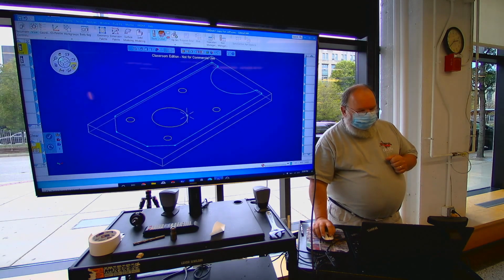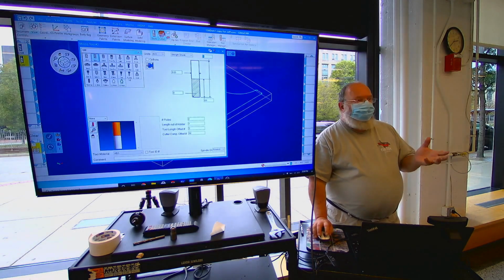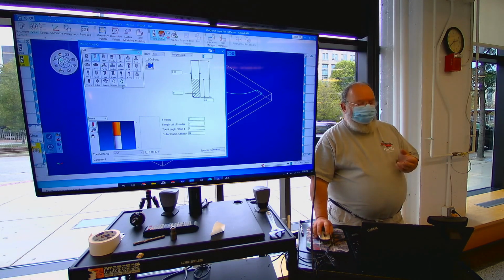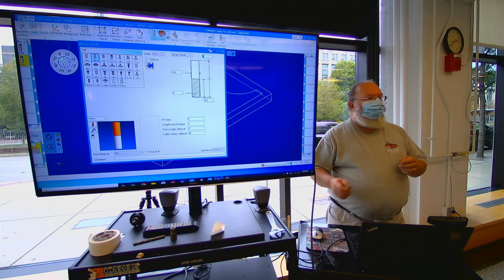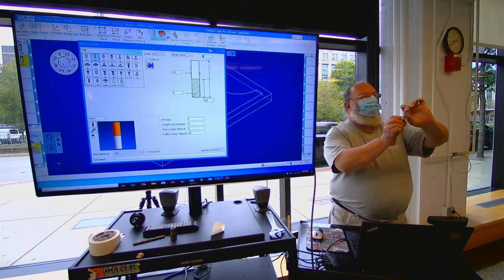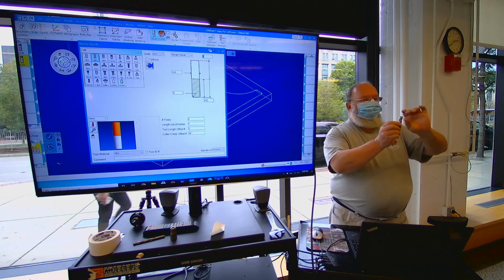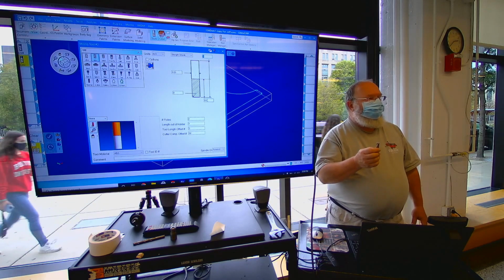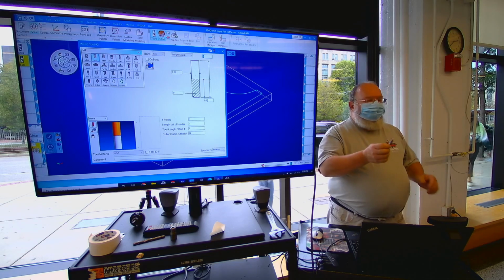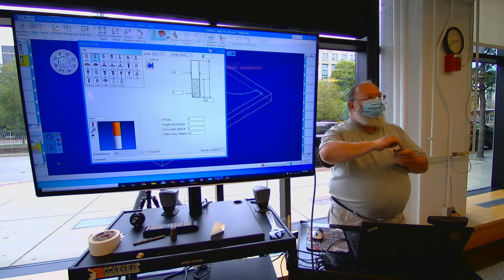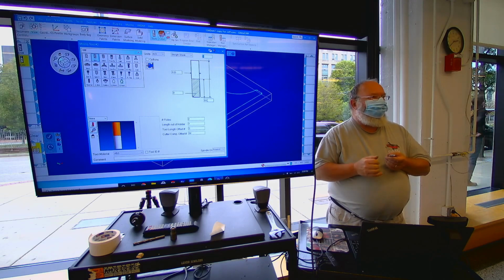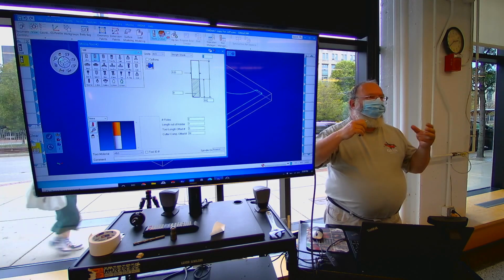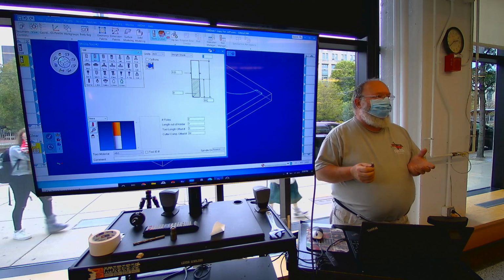I'm going to open up tile number 2. That's another end mill, only it's 1/4 inch, it's twice the diameter. This refers to the length of the cut, or the length of the cutting edge. Or in industry, they call it the flute length. Now, I don't know why they decided to define the material that isn't there, but they do, they call that a flute. So whatever flutes it is the same amount of cutting edges.